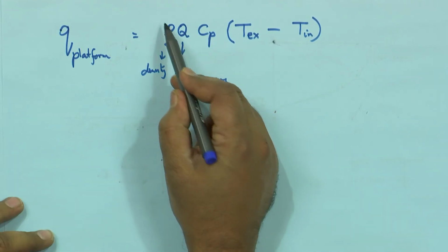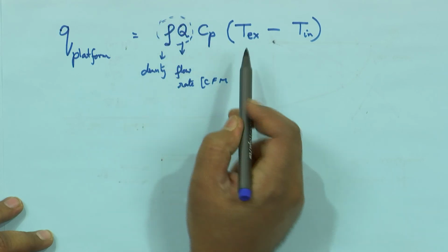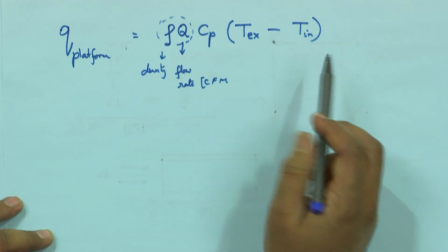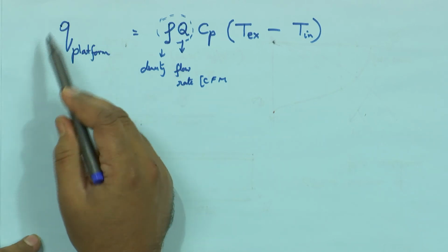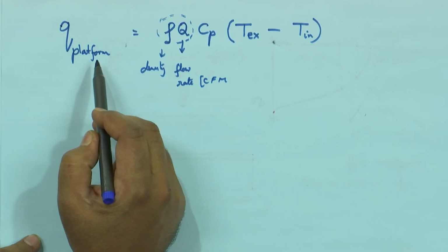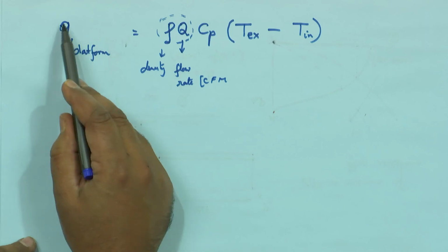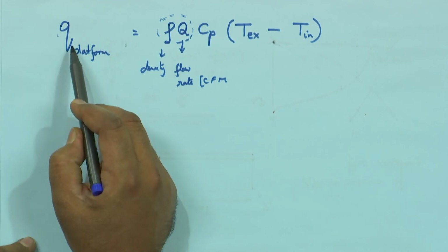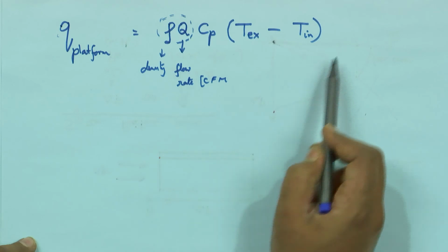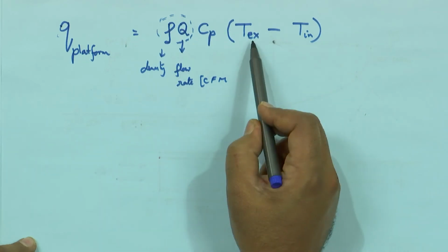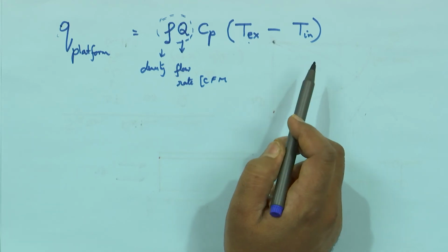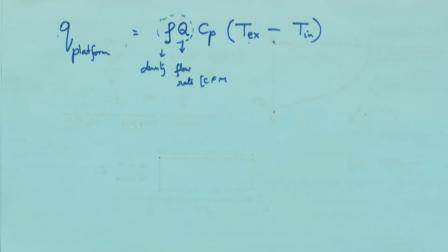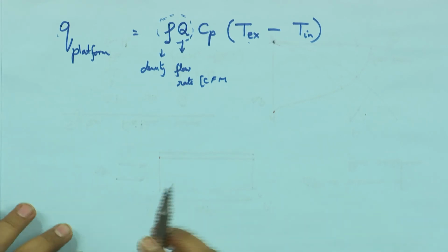I brought in this mass flow rate of air at a temperature T inlet. As it traveled through this laptop, it picked up heat from all the components, and by that it heated up. So, this heat that is released or absorbed is equal to the increase in internal energy or enthalpy of this cooling air, and so this equation has to be balanced if I am assuming the entire heat is lost by the cooling air, right. So, what does this do?